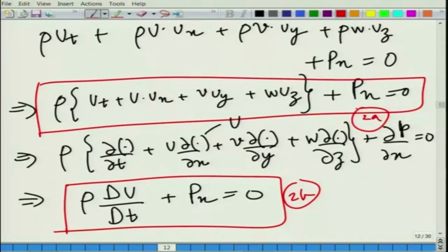Let us not consider the mean flow for a while, let us work only with stationary flows. So, we will probably need to have a closer look at this. If you remember our last discussions, when we began the process of linearization, right now we have not done any linearization, they are just the equations, Euler equations, because inviscid flow is there. What we need to do in the context of acoustics or small signal equations is to start to linearize